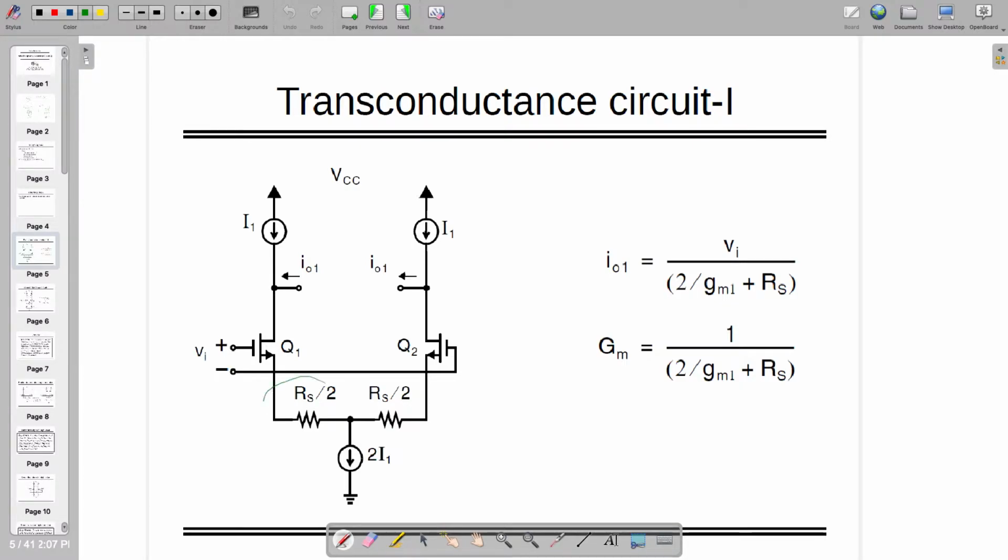So when you are adding one resistance, this becomes linear, because I'm expecting that GM, for any value of V in, it has to be linear. So how to make sure that? Yeah, source degeneration is going to give you linear, but how? Do you know this? Now you found out or not?